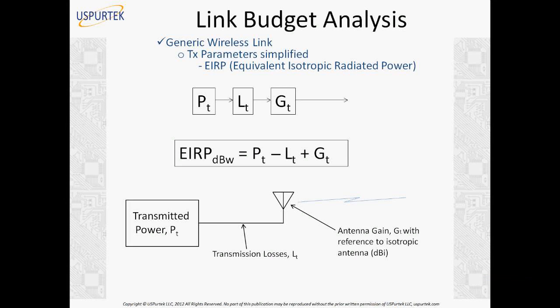Okay. What does it signify technically? So somebody asked what does EIRP signify technically? So technically we are taking into account the transmitter gain and the transmitter losses. If you see in the picture here, in the slide here, the transmitted power is PT. Like we say, I have a transmitter which transmits 40 watts of power. But that ultimately means nothing unless we exclude transmission losses. We subtract the transmission losses because of what cable I am using to transmit from my equipment to the antenna. I have to subtract my transmission losses, but I have to add the gain of the antenna too.